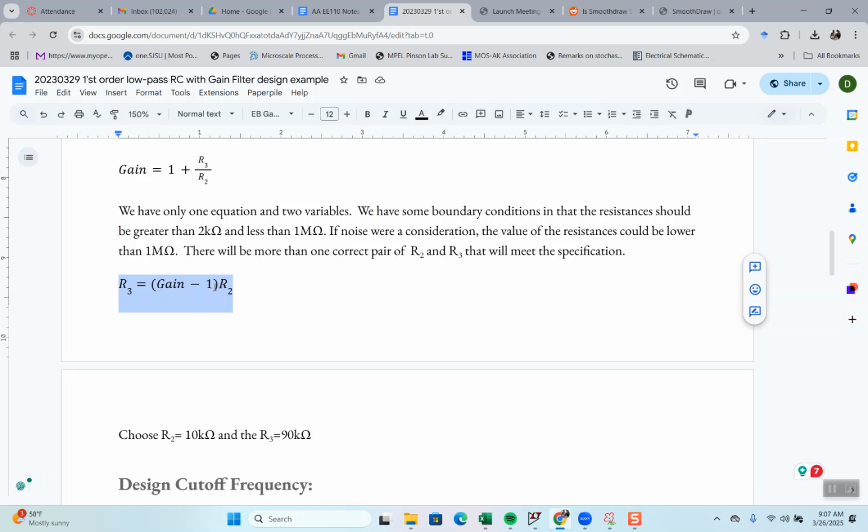Now you can kind of get away with 2 kilo ohms. The reason, besides limiting the current, which limits the power, is that the op amps stop working below 2K. You can see it in their data sheet when they'll say open loop gain measured with 2 kilo ohm resistor and it's lower, measured with 10K and it'll be higher.